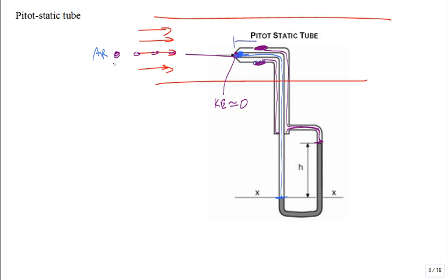So over here, we had the pressure, the flow energy, plus the kinetic energy in 1/2 rho v squared. That seems funny, Professor. The units on that are not energy, it's pressure. I can see it. It's pressure. I know it's pressure, but it's energy per unit volume. That's how you can interpret pressure in Bernoulli's equation.